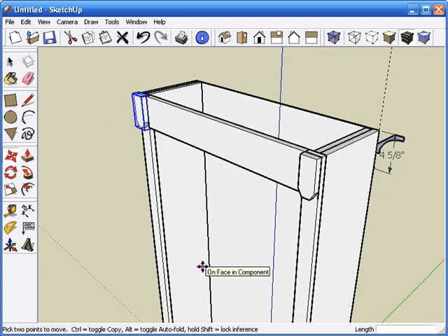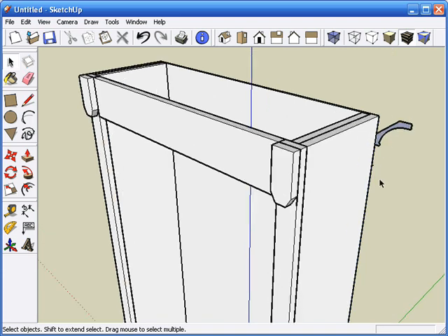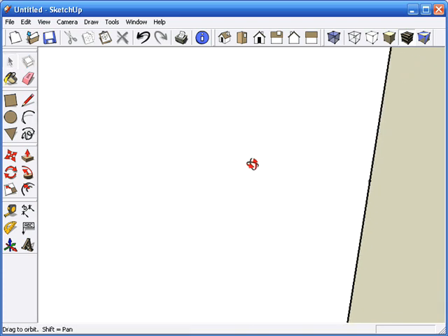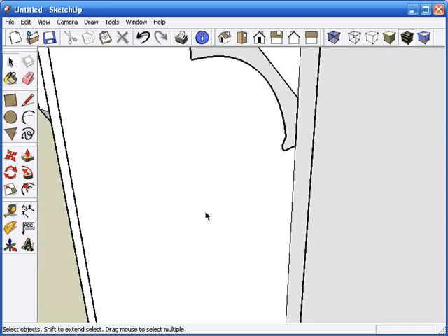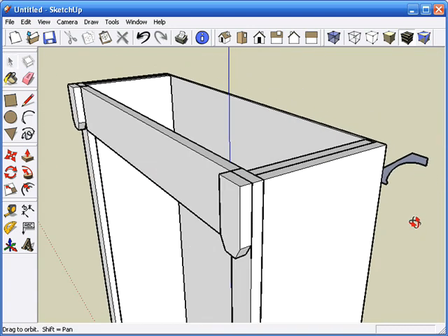Now let's do something fun. This is where you run the molding. We're going to choose the cursor, the select tool here, and get rid of this measurement mark. We don't need that anymore. I'll press the delete key and it'll disappear. And we don't need this construction line here either. I'll press the delete key and that'll go away. And there's some construction marks down here too, probably. Yeah, there's one. Let's get rid of that. And that's gone. So we don't need any of that. Just clean up the drawing a little bit.